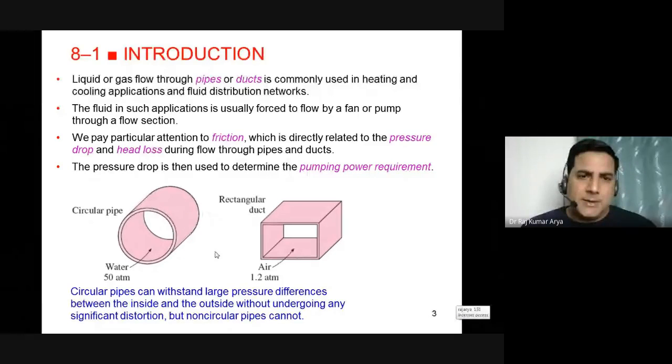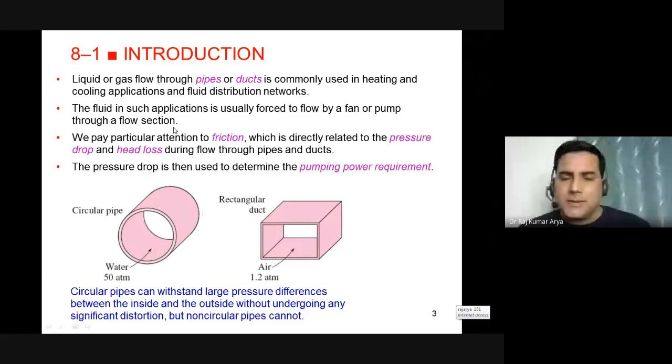You need a pump to drive the flow in a closed channel, but you can also do without a pump, because you can have a gravity type of slope, just like distribution of water from an overhead tank. For all municipality water or hostel supply, you fill up the overhead tank once, after that you just open the valve and you get the supply.